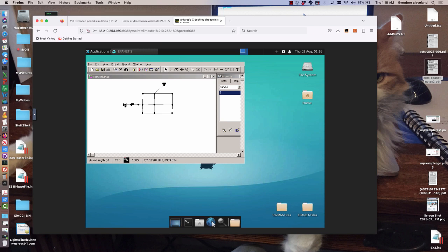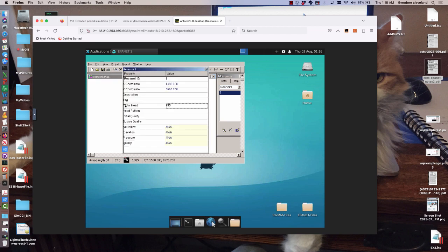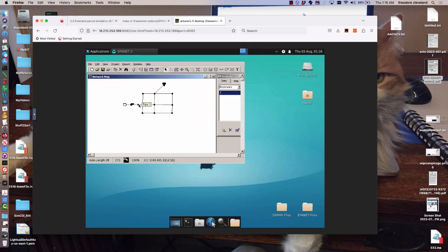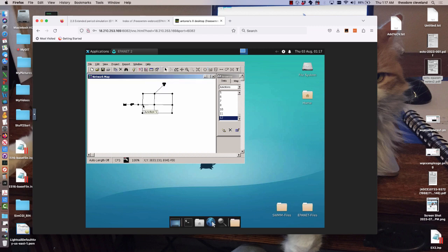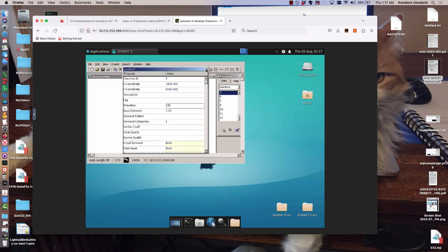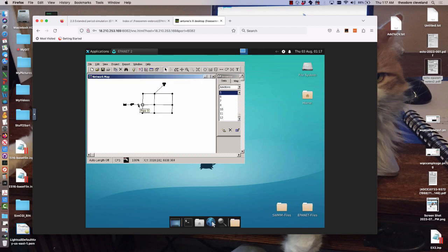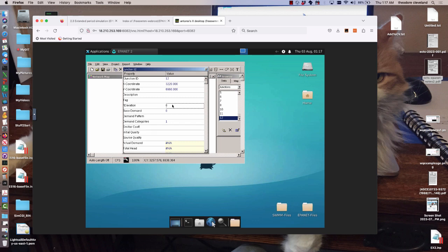And let's look at the supply reservoir. The supply reservoir has elevation 155. The first node in has elevation 0, so that's gravity flow. That's probably a mistake. That node has 155. Let me fix this because that can't be 0. It makes no sense.